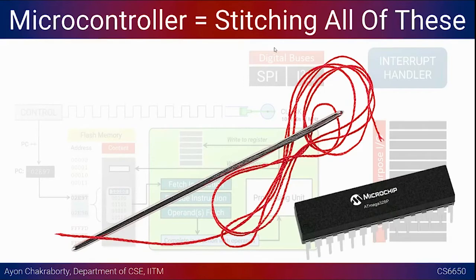So the microcontroller course will teach all these concepts. We have spoken about this AVR core, that is the core CPU part. We have spoken about so many registers, the controller logic, the clock. You also have these digital buses, analog buses, ADC, timers, GPIO. All these things come in a package, and this is what is known as a microcontroller.